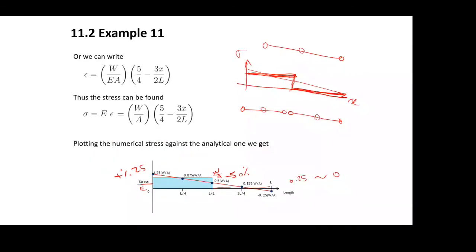The two noded elements, so this is one two noded and second two noded. So this one noded element will only have the constant to fit into this constant, and a constant can fit fine in there, and a constant can fit fine in there. So this element would work just the same way like this one.